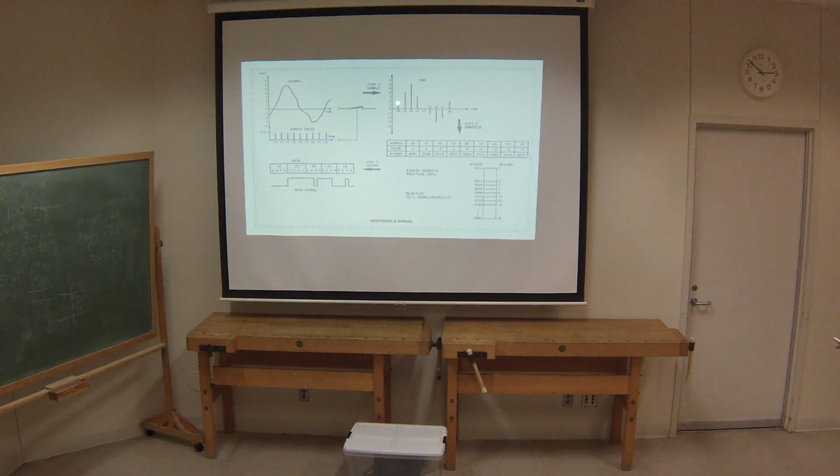And if we did the same here and amplified it and put it to some speakers, we'd hear audio still. Go with me on that? It's not digital yet. If you drew that little capacitor and close your switch long enough to charge it to the appropriate value, then you open the switch, that capacitor is going to stay at that voltage.